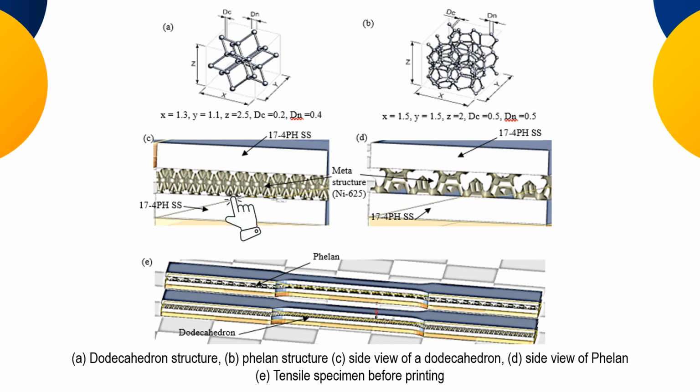Now, what will happen? You can see the length of the link and the angle of the link is different in both cases, just as an example. I am interested in having a tunable tensile property. Similarly, we can think of tunable compressive property, tunable torsional property. This helps me in a big way in controlling the implant properties, customized or tunable to be near the natural bone. That is one of the advantages, or the flexibility, that I am getting with this type of metal printing.